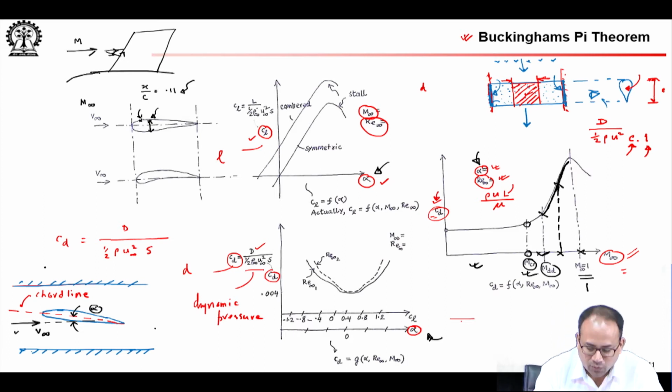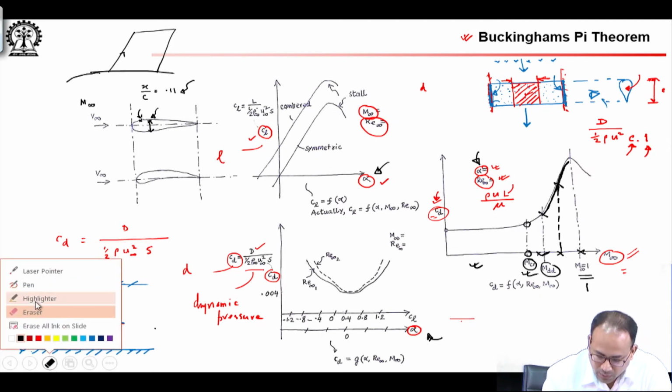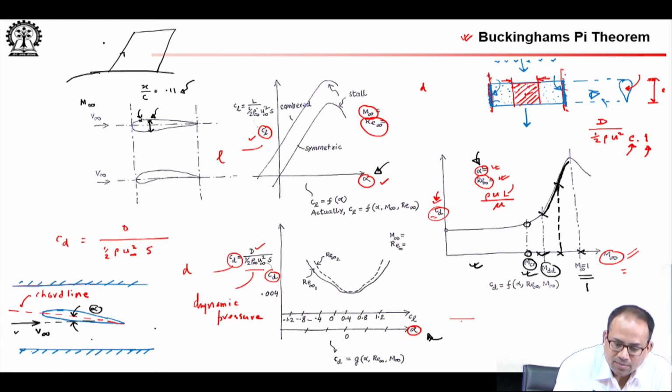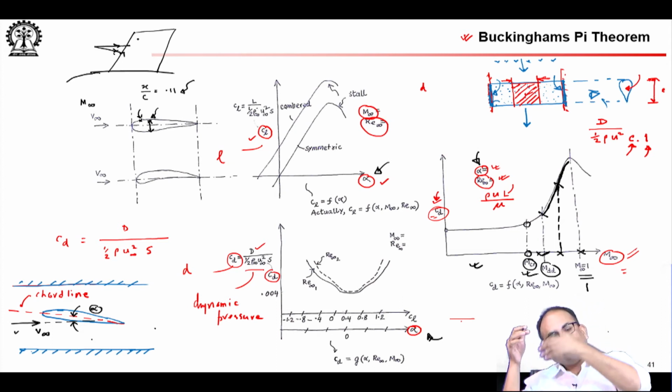So, if you think of the component that is normal to the leading edge of the wing, whatever component is normal to the leading edge, that one is actually less than the free stream Mach number. So, the leading edge will see, because you have swept the wing back.